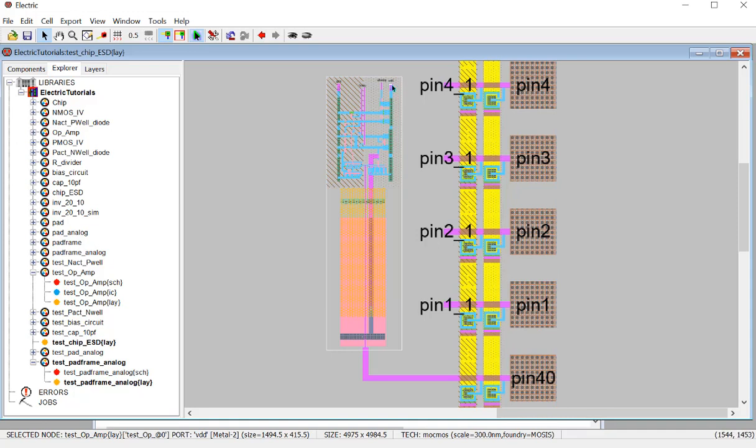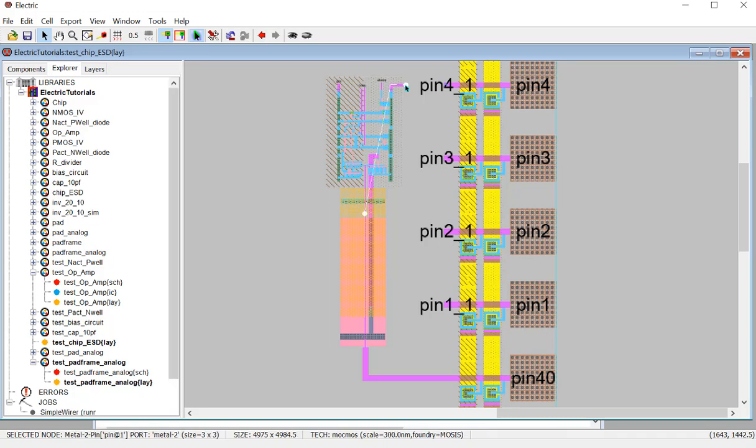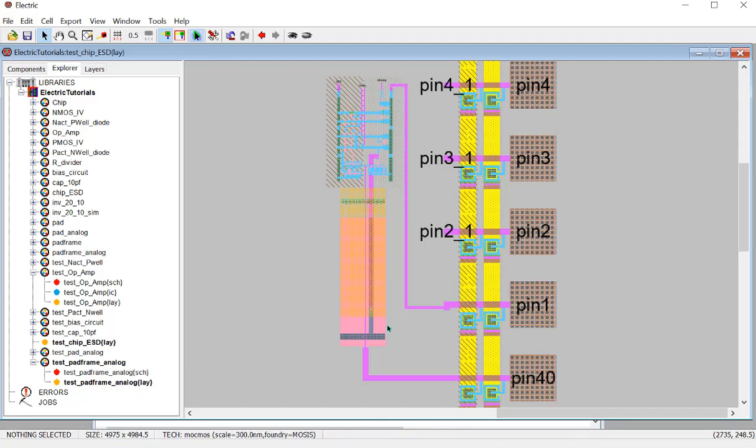So when you are trying to get this wire out from the chip, you want to press Control, and at the same time, you want to press right click. So the wire is out, it just comes out. And now you want to come to here, keep the Control being pressed, and then for here to connect to this pin, you don't need to press Control, because you can see that whenever you hover this mouse to this port, it shows up the little cross here. So which means it's going to be connected to here. I'm going to directly just connect it.